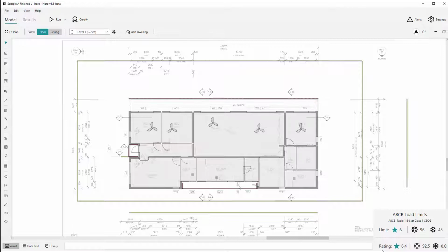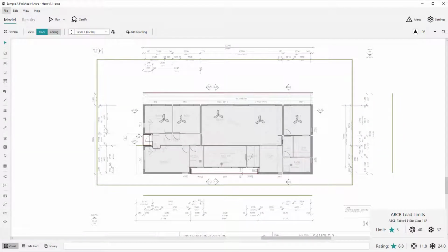So to start with, for the star rating requirement for a single dwelling project, this is typically 6 stars based on the current NCC 2019. However, for NCC Climate Zones 1 and 2, there are concessions available to reduce that to 5 or 5.5 stars based on having an insulated outdoor living area and/or ceiling fan, and I'll explain how those are entered and assessed slightly later.